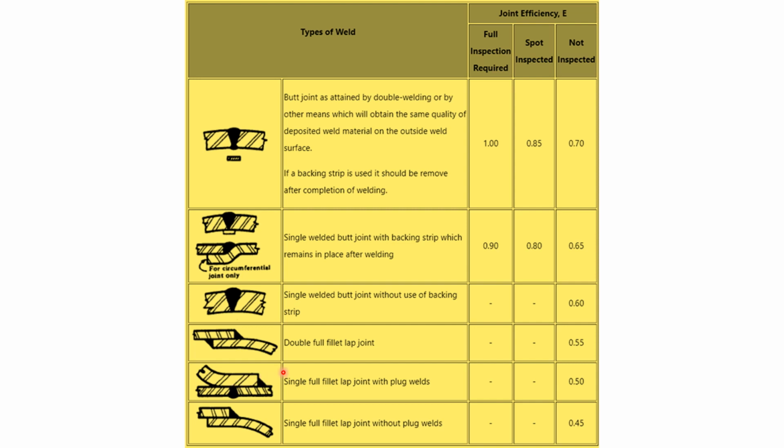Type 5. So in type 5 we use a plug weld. Okay. You have a shell here, and you have a head, but here you put some plate and you plug it, just weld it thoroughly. Or you put a back strip, a strip over here, and you weld it properly. This welding is not commonly used in a pressure vessel company. Type 1, type 2, type 3, and type 4 are most commonly used. Type 5 is not mostly used.